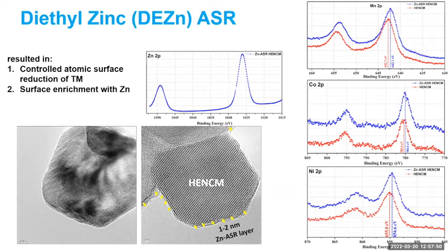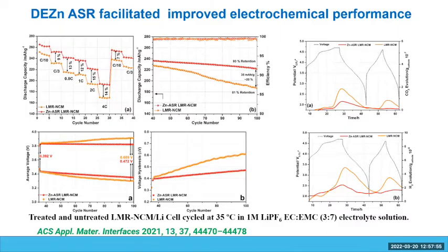And again, we see a reduction of the transition metals on the surface. And when we follow the gas evolution, there is suppression of gas evolution when we are coating our material, and significantly improved long-term stability of the battery. This is the red one, for the coated. It means for 100 cycles, we are cycling our battery, and we have a capacity retention of 93% compared to significantly less. So this is about 81% capacity retention of the active material, which is not protected.